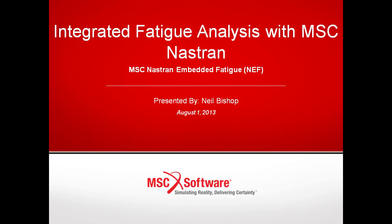So I'm going to talk about solver embedded fatigue. In this particular case, I'll be talking about Nastran embedded fatigue, but the concept is general. It's a very simple concept with quite dramatic consequences, and that is to take something that has always been treated as a post-processing operation, that is fatigue analysis, done after the calculation of stresses, and combine that simultaneously with the stress calculation. So that simple conceptual change results in quite dramatic benefits, and that's what I'm going to talk about over the next 30 or 35 minutes. I'm going to try to leave plenty of time at the end for Q&A.